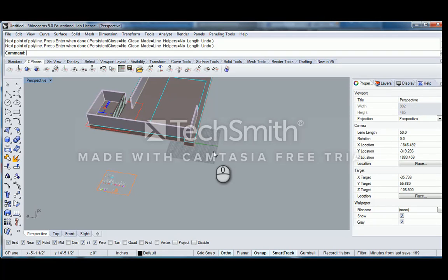So I believe when you're in a single session of Rhino on the same computer, it will let you duplicate those settings across. But say you're working on your laptop, and then you're working on your desktop, or you're on a school computer or something, you can actually export out your aliases and save it as a text file. And then what I would actually do is put that in your email or on Dropbox or on a jump drive or something that you can just quickly load onto whatever interface you're working on. That's the easiest way to do it.